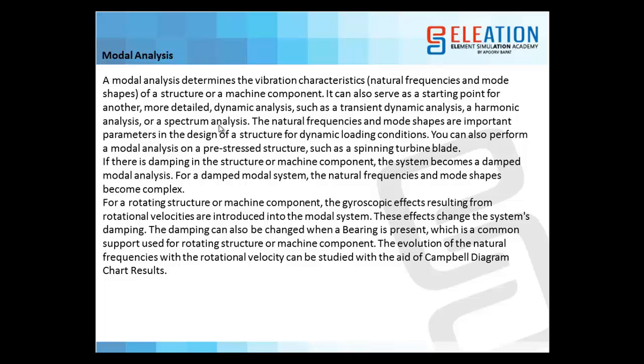So modal analysis determines the vibration characteristics, that is the natural frequencies and the mode shapes of a structure or a machine component. It can also serve as a starting point for another more detailed dynamic analysis, such as transient dynamic analysis, harmonic analysis, or spectrum analysis. So if you want to perform transient dynamic analysis or harmonic analysis or spectrum analysis, the first thing you have to do is to perform the modal analysis to find the different mode shapes. The natural frequencies and mode shapes are important parameters in the design of structures for dynamic loading conditions.